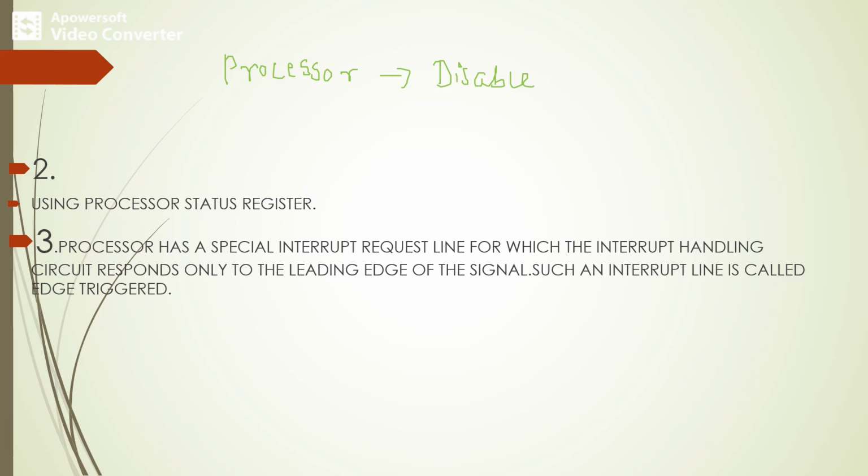In advance of this, the processor should save the contents of the PC and the processor status register on the stack. So the processor will save the content of the PC as well as the processor status register, that is PS, within the stack.